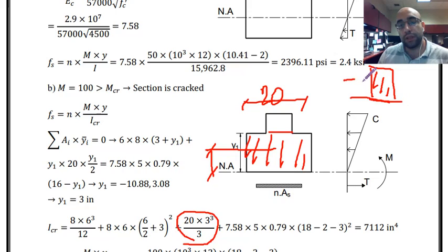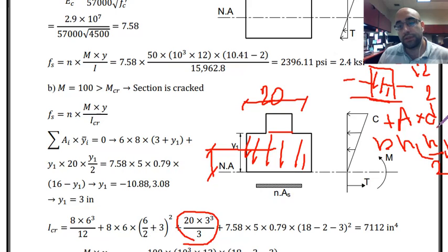You know, when we were looking at the centroid of the shape itself, the moment of inertia was bh cubed over 12. And now if I want to calculate it about this bottom line, I have to add this term, area multiplied by d to the power 2. A is equal to bh, and d is equal to h over 2, and now it should be squared.